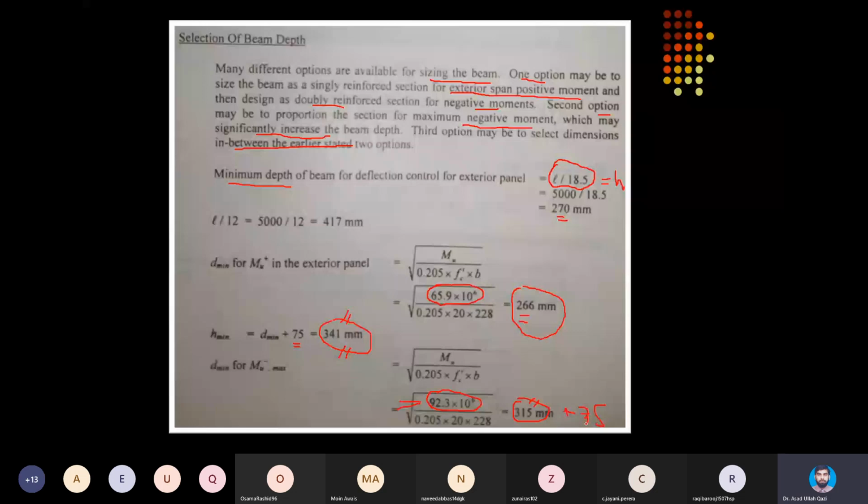So while designing them at various sections of continuous beams, we want to keep on comparing the demand with this rho minimum. So when I multiply rho minimum with the web cross-sectional area, considering that I have selected now the D350, it comes out that nowhere I am allowed to go below 266 millimeter square in reinforcement.